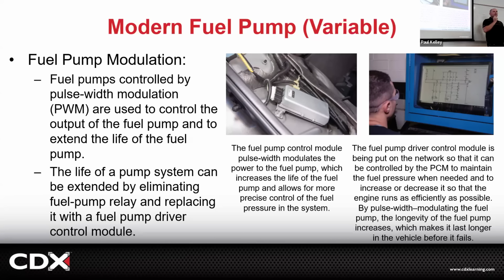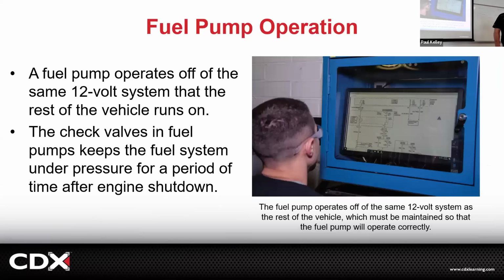That's gotten a bit harder to diagnose. Now you've got to make sure the fuel pump control module is getting what it needs and that it's putting out what it needs. So if your fuel pump isn't running on one with a fuel pump control module, you've got to determine, is it the control module computer or is it the actual pump? And sometimes to do that, we've got to look for a waveform, right? It's a little more tricky. But just so you're aware, we'll see what we can do to get one up on a picoscope or something.